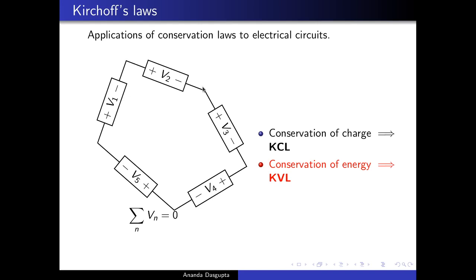Same thing. Although of course, remember, by convention we have drawn all these voltages as drops, but since the law tells you that the total sum has to be 0, some of them must be negative, so there will be rises somewhere. So although I am saying that the electrical energy drops, that's just conventional. If V1 is negative, then the actual electrical energy stored in the charge rises. But anyway, as you go all the way around, the total energy dropped by the charge is the amount of charge times the total change in potential.